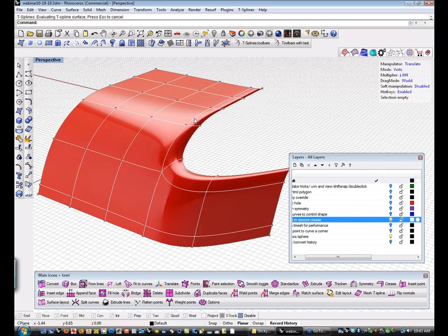Okay? So if you run into a situation like that, look for two things. Look for stacked verts that aren't welded, and look for red dot verts, which are essentially the same scenario, but it's a vert that's just out in space that doesn't have any relation to anything. Either delete those or weld them to something else, and most of your modeling worries will disappear. The easiest way to do that is to drag select and check to see if you have any stacked verts.